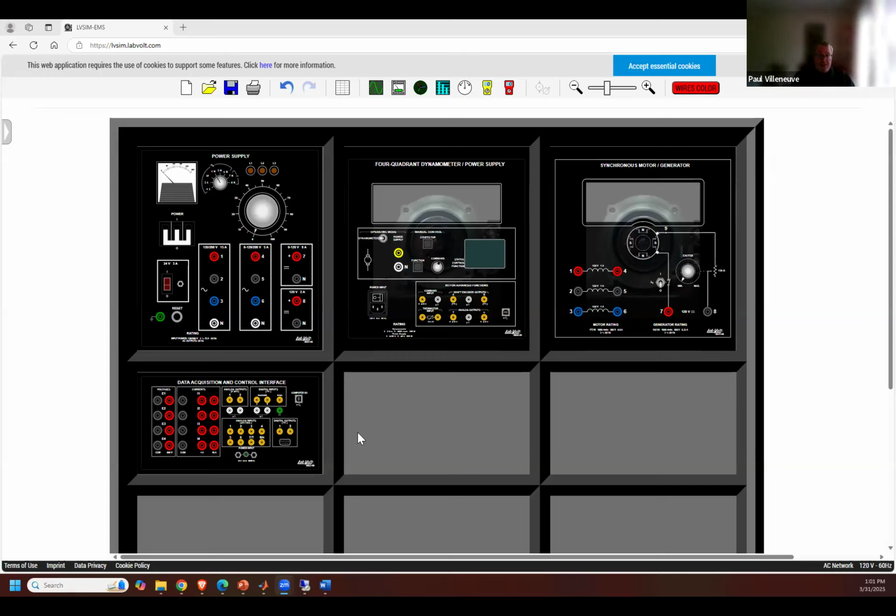So in a synchronous machine, what we realize is that we've got to have a fixed magnetic field on the rotating part. Okay, there are some exceptions where the fixed DC field is on the stationary part, but those are pretty rare. They do exist, but if anybody wants to know where you find them, please seek me out. But for the most part, we'll assume that the DC is going to be on the rotating part.